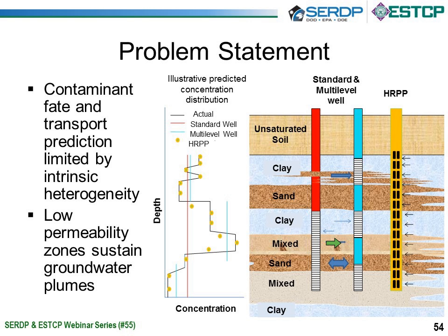And so the idea that we had was to basically adapt a technology that's been used for sediments to groundwater applications in order that the information that you want to receive is not dependent upon hydraulic conductivity. So a direct push technology that can be used at high resolution and be able to return data desired, regardless of the hydraulic conductivity.